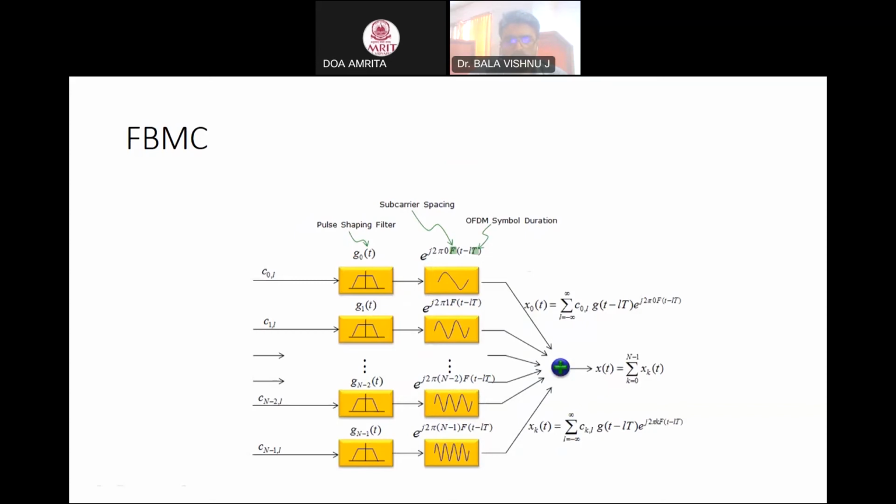That plays a crucial role in designing the low noise amplifiers of a transmitter and receiver. To overcome that problem, we use the filter bank to improve the resolution of each subcarrier, and also to reduce intersymbol interference, which affects the other symbols, and also intercarrier interference. This is achieved by designing a filter bank for each subcarrier.